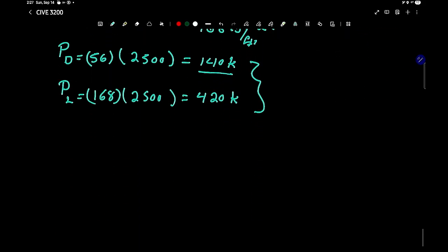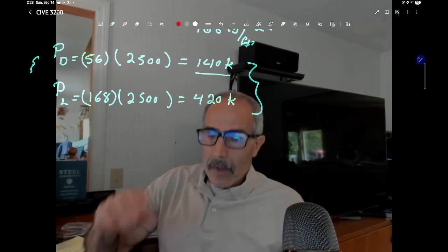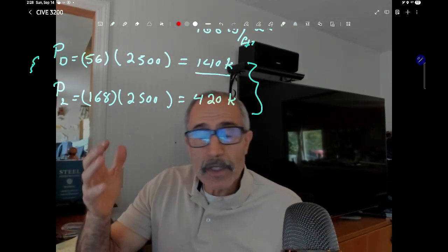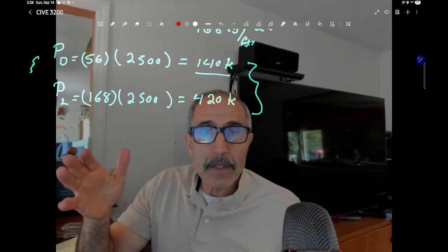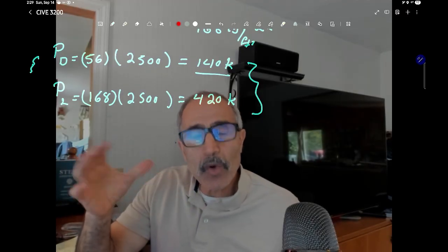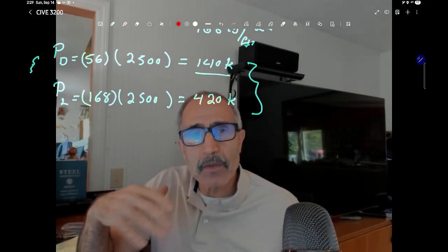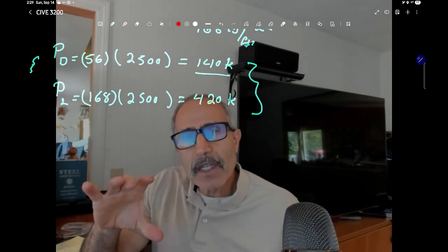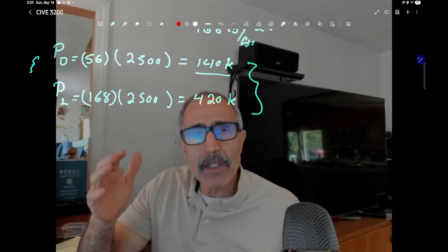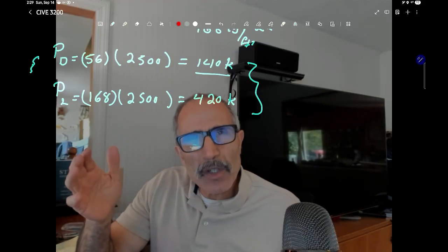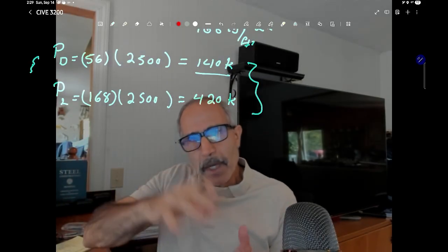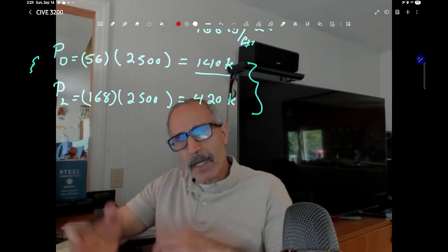And then one thing we're gonna do: if you're an experienced designer, you automatically say, okay, I'm going to use W14 by 100 or this or that. But if you haven't done this and you don't know what to pick, normally W12 or W14 or W16, around that area, is a good size to pick. Sometimes the architect might let you know. So let's say we're going to use W14, but we don't know what size. We're going to guess at the size, and then we're going to come back and do the analysis on it.